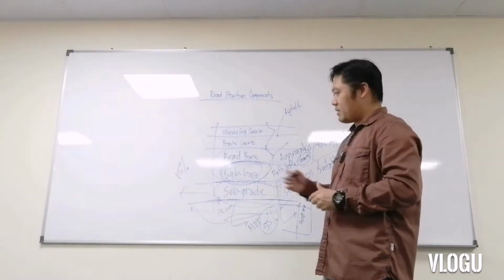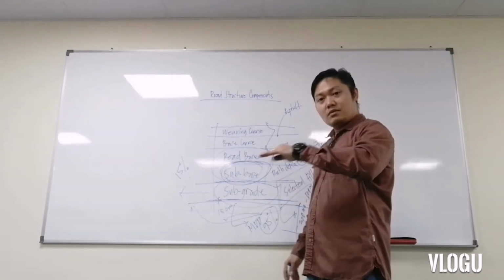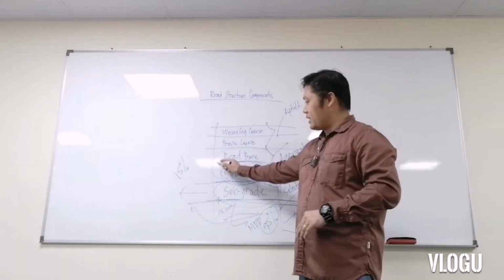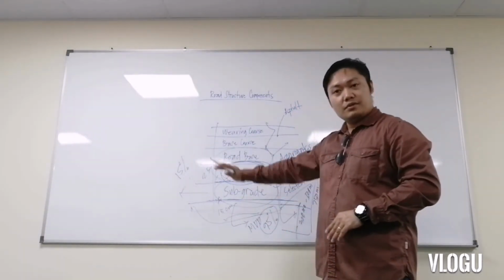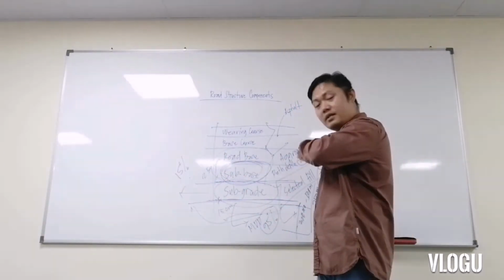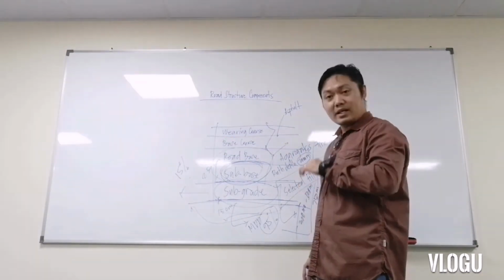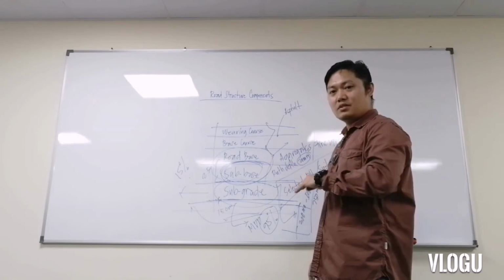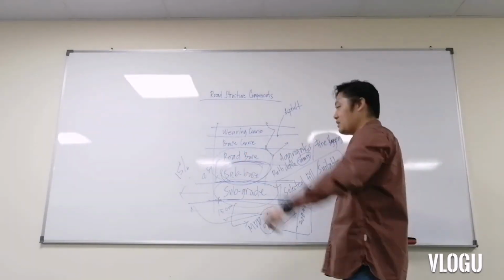Now, after we conduct this, it depends sometimes on the thickness of the subbase. Sometimes the subbase will differ based on road design. So let's say, for example, we have 250 mm. So we are going to spread the subbase in 2 layers in order to attain the maximum compaction during the rolling operations.